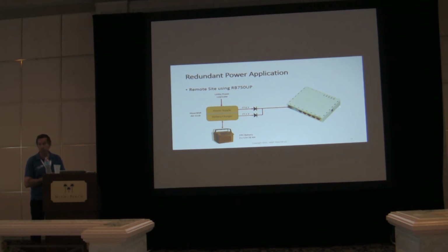Inside of the MikroTik routers, they've got diodes as well, and so you're going to read about 0.6 volts or so less. By the time it gets out to one of these ports, it's going to be 26.4 or a little bit less than that, depending on what diodes are being used. So don't think there's something wrong when you do system health and you see the voltage is not what you're putting in. It's what's coming out of the router.